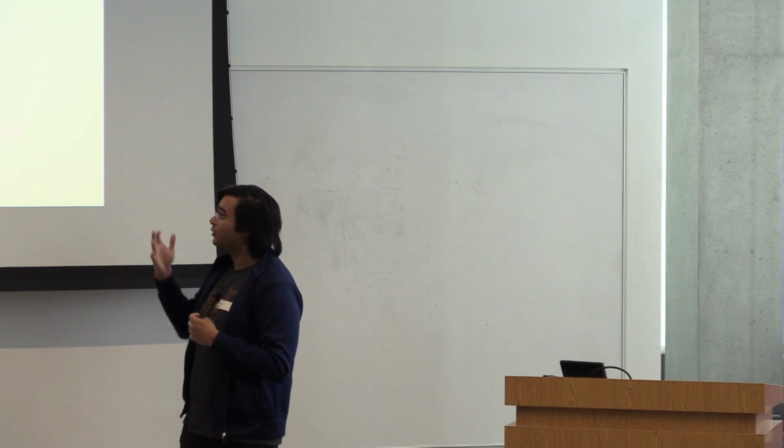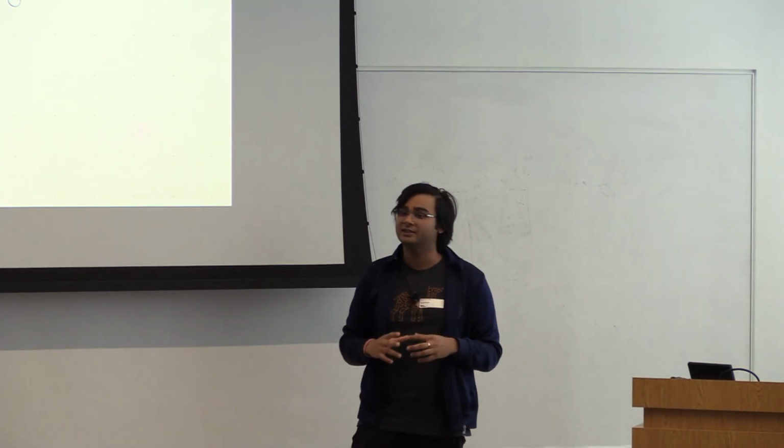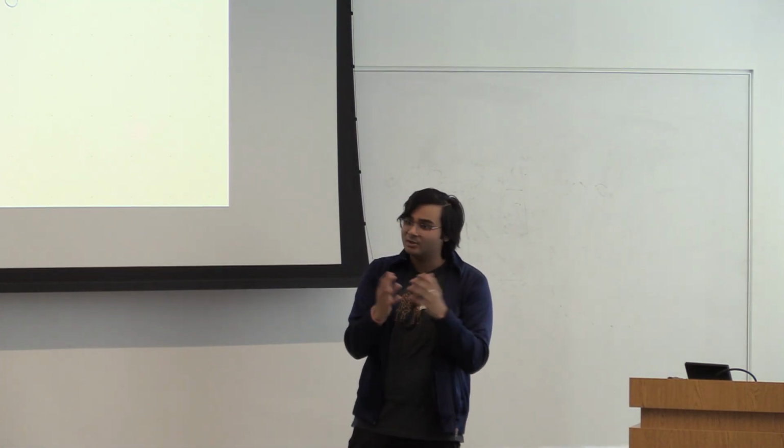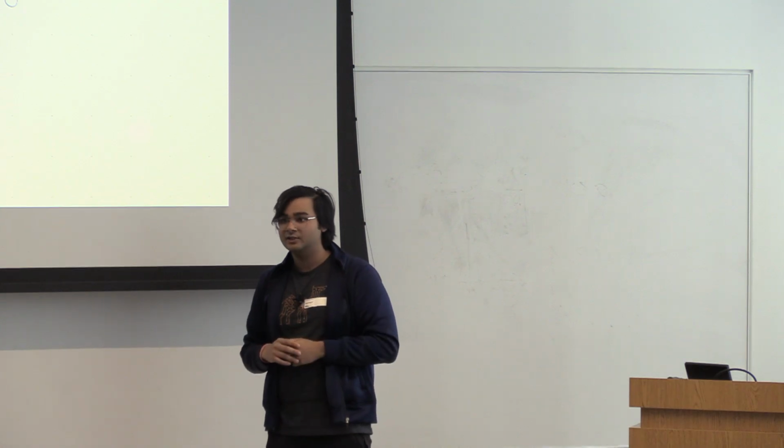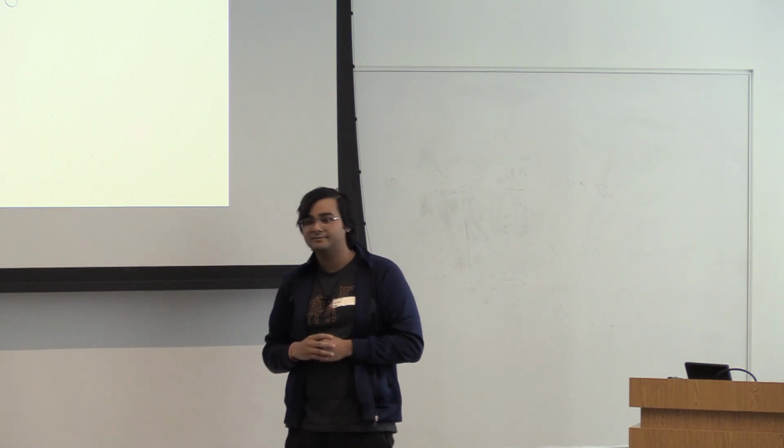So what I am showing you is the combinational interface. Hardcaml defines this other type called signal.t, which has combinational components, registers, and memories. And those three things together make a full circuit, like hardware description language. And registers are also defined in exactly the way you think. They have a clock, clear, reset to, and so on. But once you define those two other functions for registers and memories, you can get a full HDL. Good question.